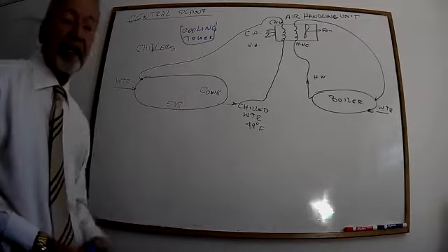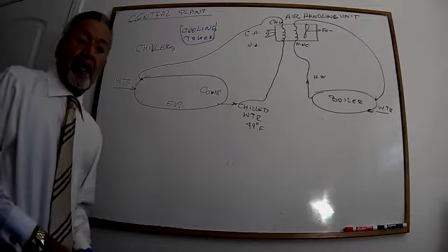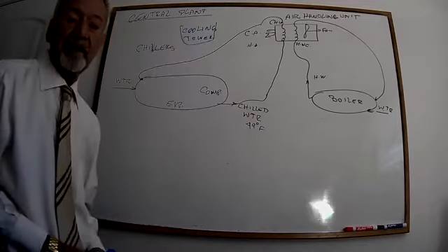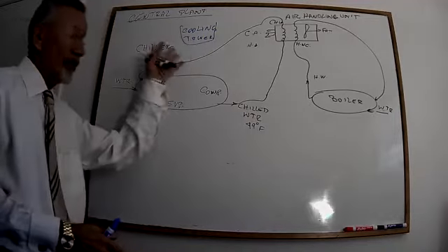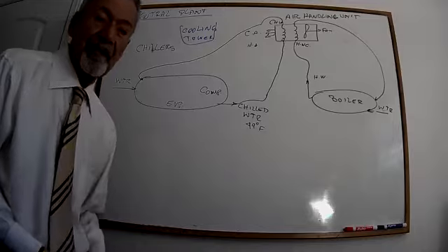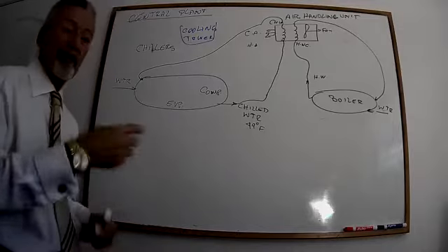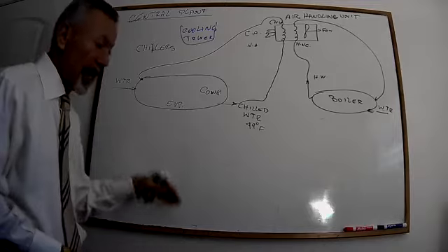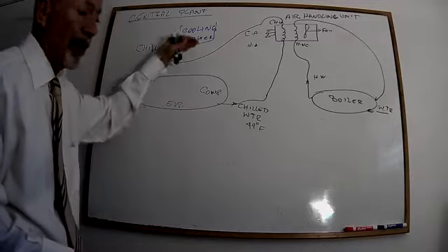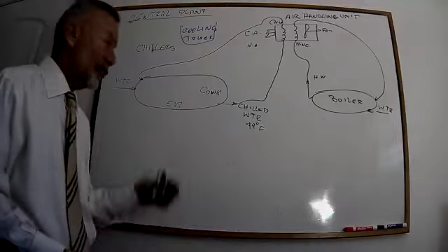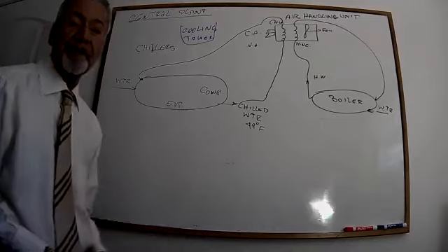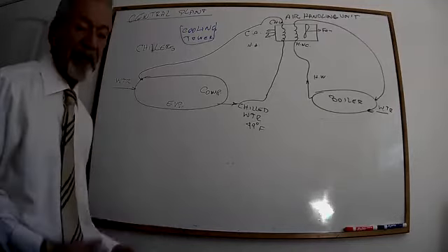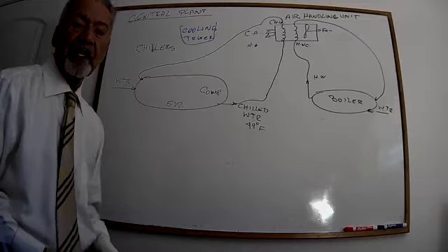That's what that is. And this cooling water has its own pumps, pump 1 and 2 and 3, sometimes 3 pumps in order to circulate all that water. It depends how many chillers you have. If you have 3 chillers, you have 3 pumps here. If you have 2 chillers, you will have 2 pumps. So it gets very sophisticated, very complex.